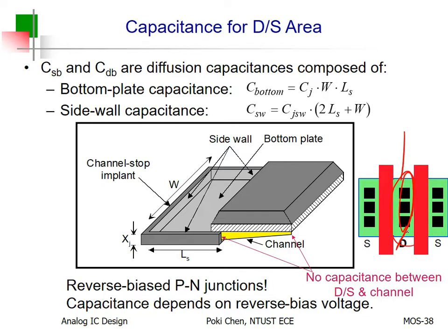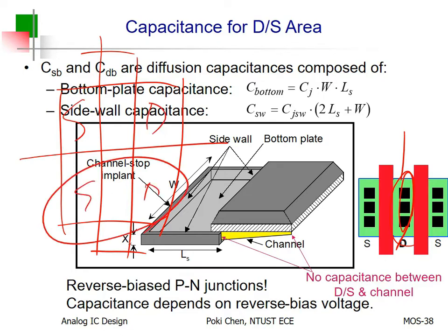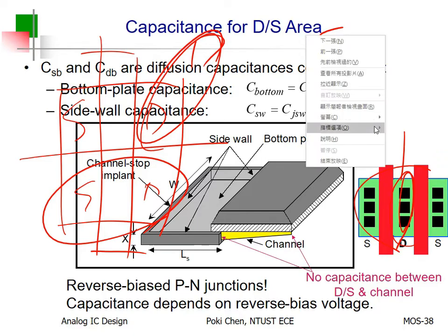So it means what? If you have a long, I need to say wide transistor, don't do any layout like this. You had better split it. Okay, you say, hey, this is source, that is drain, and this is also source and drain. Then you flip it to become drain and source. Then overlap the drains. Look like this. So totally, the overall parasitic will be reduced.